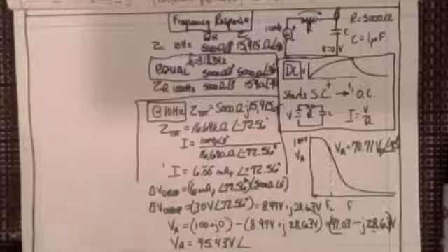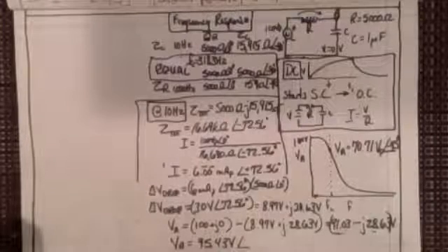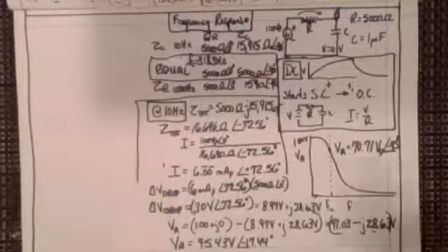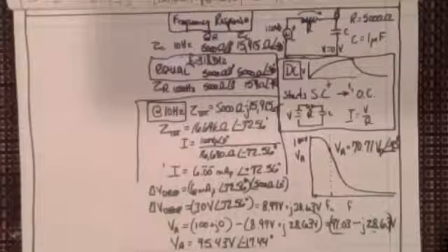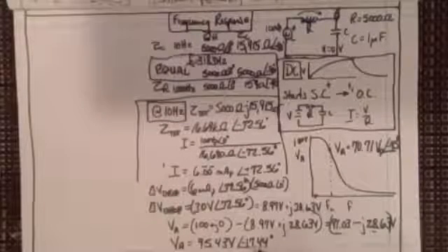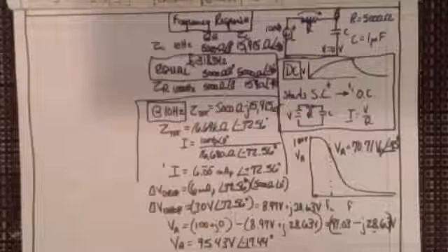So let me give you that angle. 28.6 divided by 91.03, and then take that quotient and find the inverse tangent of it, and that gives me 17.44 degrees, and that's minus, isn't it? You remember, your calculator is going to screw with you, because it thinks it's in the first quadrant when in fact it's not. It's really in the fourth quadrant. So it's minus 17.